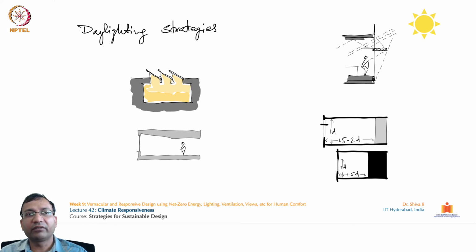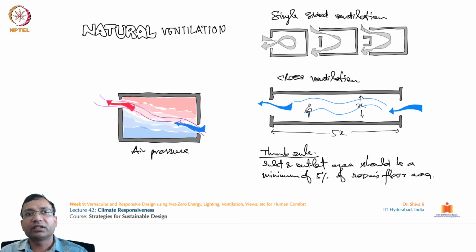Further, for promoting natural ventilation, we have some solutions here, like how we can devise openings in the building structure to control the flow of wind inside our structures. The strategic location of the inlet and outlet points also should be decided, because if we want a scouring effect of wind inside the space, to have the maximum effect, the location of these entry and exit points could be at the diagonal level. That will maximize the overall efficiency for the cooling effect.